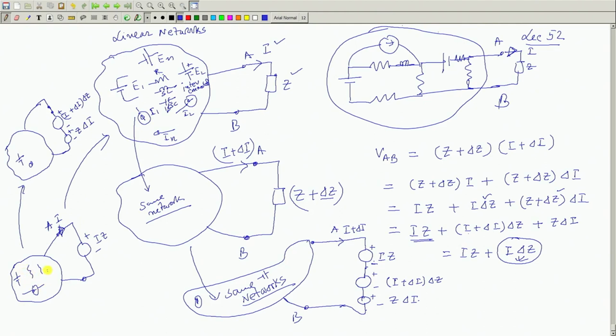No, all internal sources present and operator, and then all the sources. Now the thing is, these two sources will be, yes, you are right. Now I am applying superposition. So I will tell that these two sources are present and all internal sources should be replaced by their internal impedances, correct, absolutely. And current sources open, voltage sources shorted. So this will be the network now.